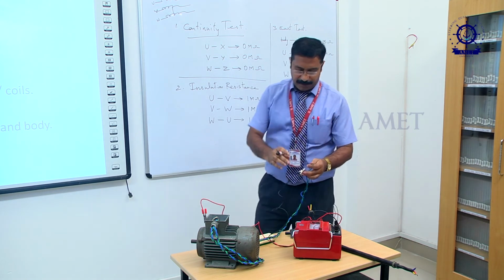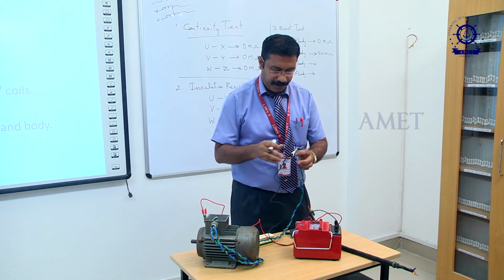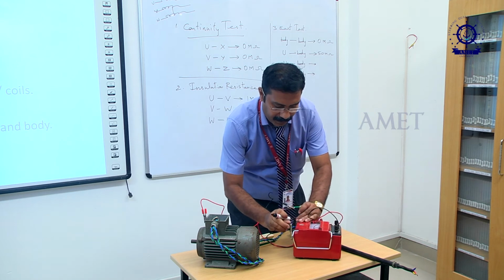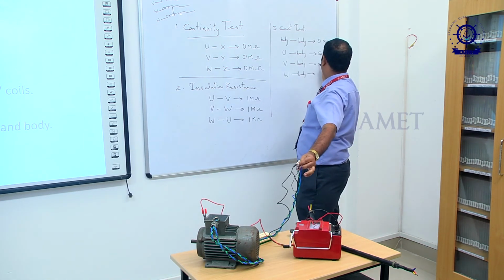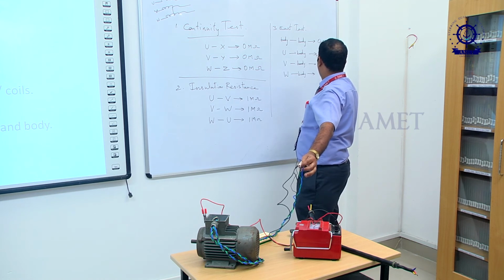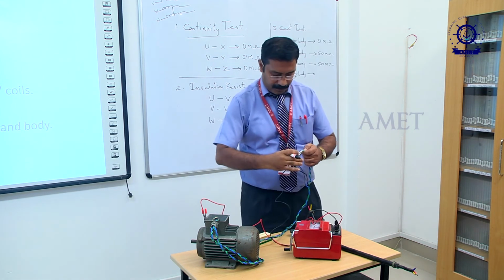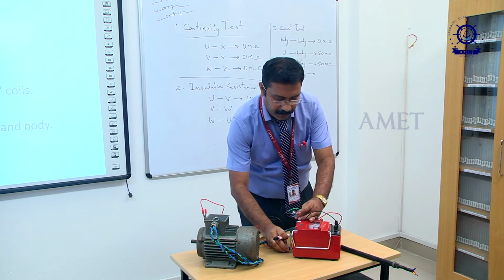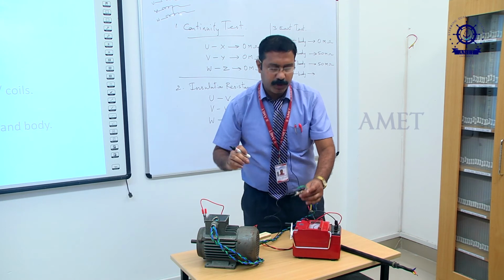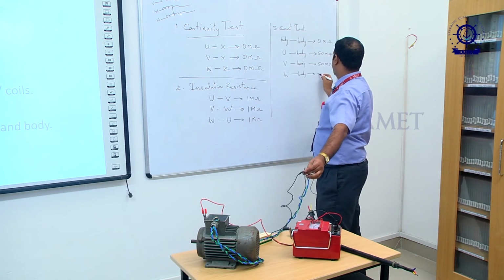For Y phase, it's also going to 50 mega ohm. For B phase, it's also going to 50 mega ohm.